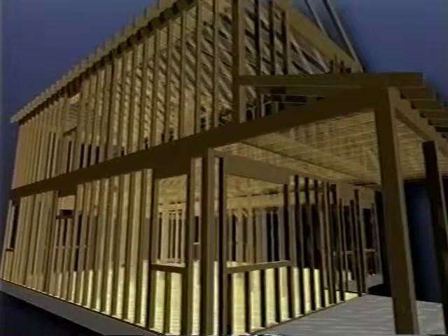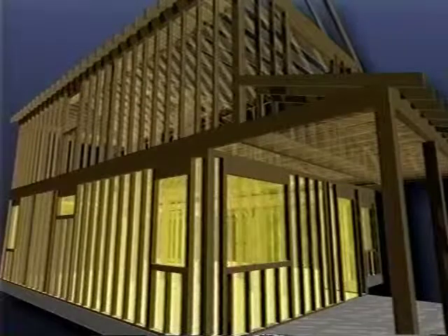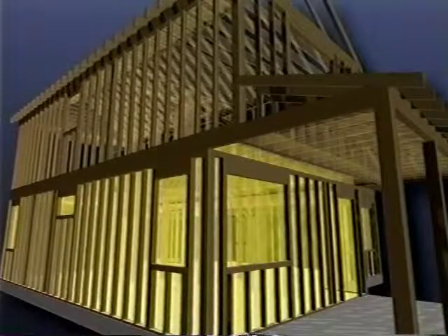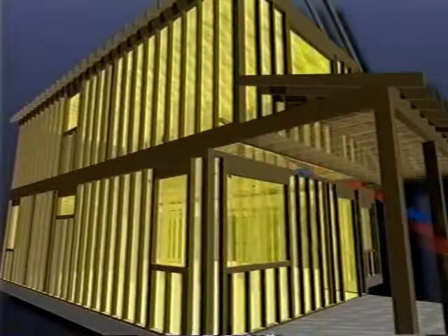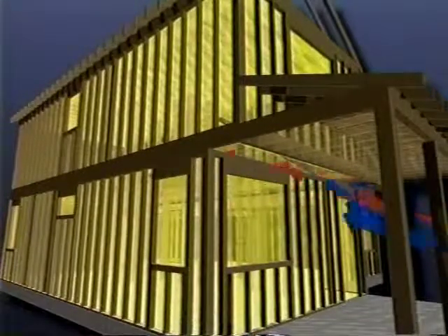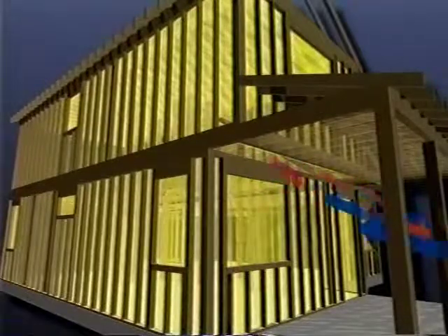As we've said, in order for the air barrier to work, it must be continuous. Holes, no matter how small, can allow indoor air to leak out and outdoor air to leak in. Here in the Southeast, one of the reasons that we're concerned about air infiltration is because of humidity. Bringing that moist, warm air into our homes is really one of the reasons why we have air conditioning, to create comfortable living environments.